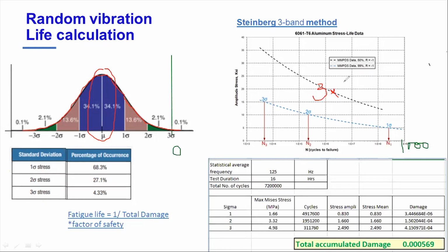of uncertainties. So you basically don't take only RMS, you take your stress outputs 3 times, so that you cover the entire band. Okay, when you take 3 times of your stress band, you are trying to imitate your random vibration cycle. You are taking care of all types of uncertainties in that random vibration input. Okay, what if terrain is more severe? What if bumps are more deep, I mean, more height, or potholes are deeper? You take all levels of uncertainties.